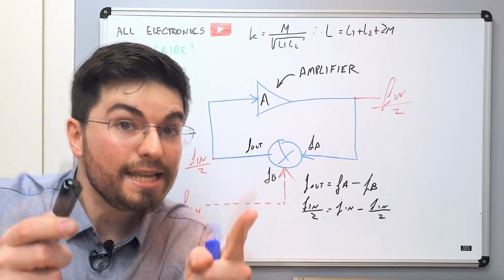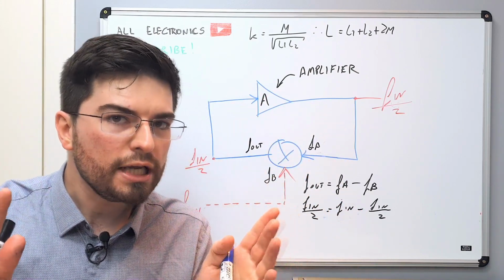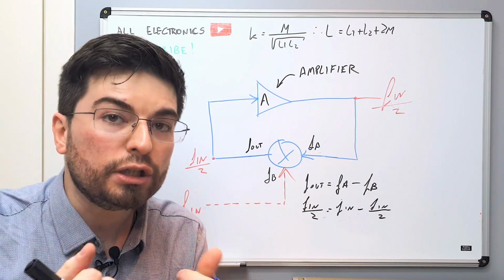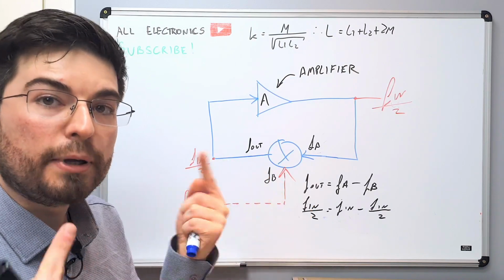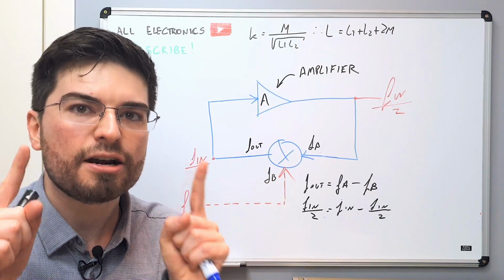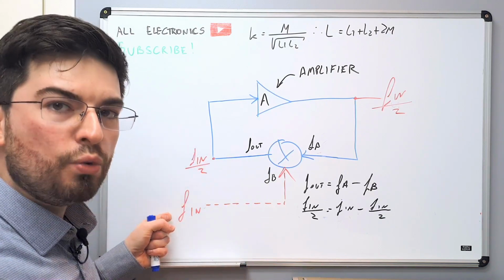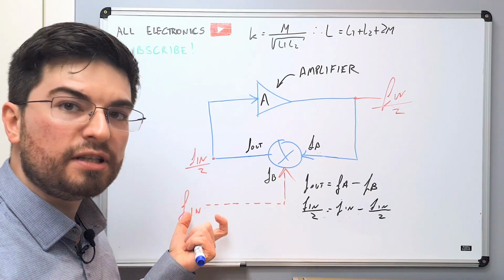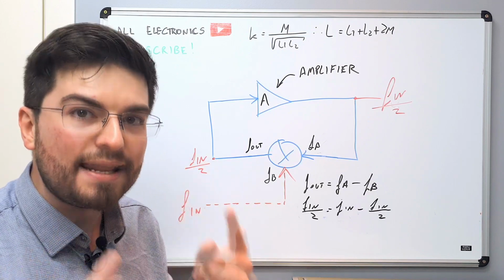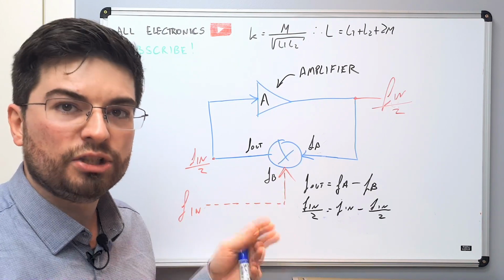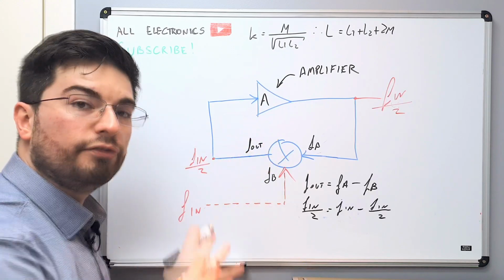This is the signal perspective, but actually we are generating injection locking of the oscillator because we are converting the energy of the input signal. We are taking energy from the input signal and down converting the energy to half the input frequency, generating injection locking of the oscillator.